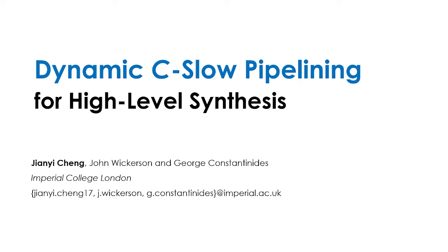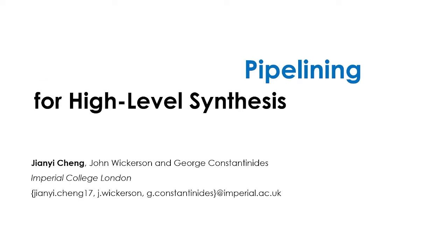Hi everyone, today I'd like to talk about pipelining in hardware. HLS tools today have now been widely used in custom hardware designs. The users can easily get efficient hardware designs by inserting some HLS parameters. One of the most popular parameters is pipelining, which exploits parallelism among iterations.